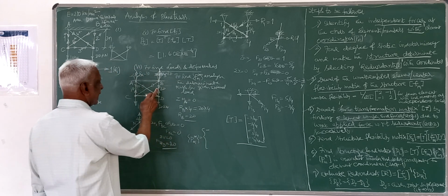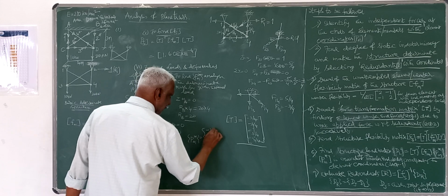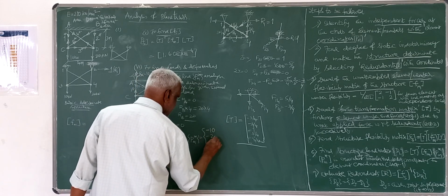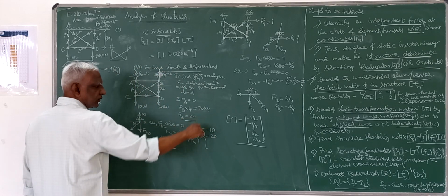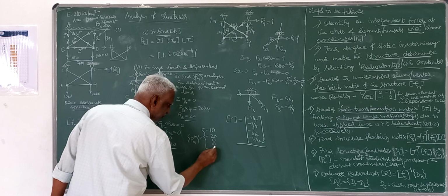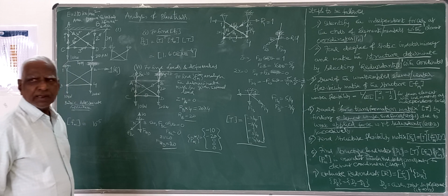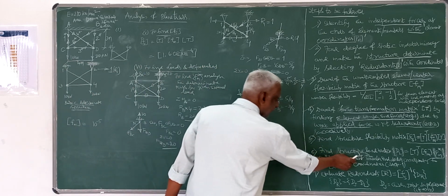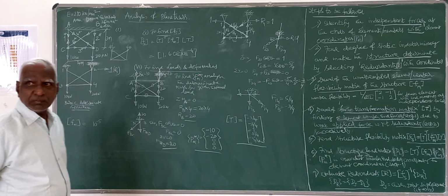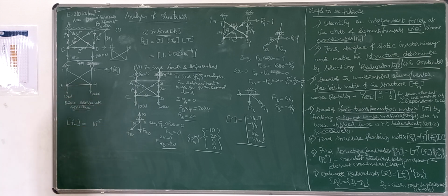So, force here in member 1, it is minus 10. Here it is 20, though it is positive, we have to reverse this direction, and force in other three members are 0. This is the PM matrix. So, here in truss problem, we have to do this particular analysis, basic analysis of the truss of the basic determinate structure for given external loading, and we have to arrive at that.